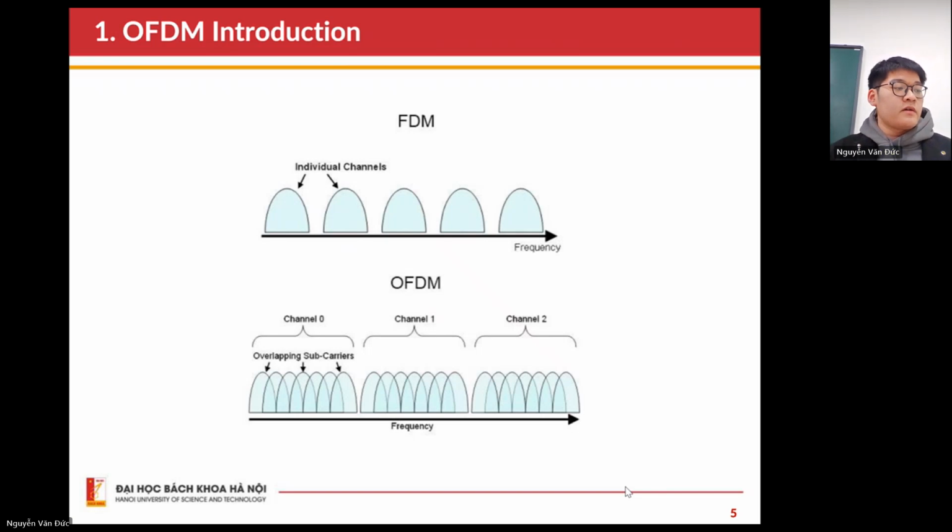I must mention our system, which is frequency division multiplexing, FDM. This is a technique that combines multiple channels with different bandwidths into a single bandwidth for transmission over a medium. Each channel is modulated with its unique carrier frequency, ensuring no overlap between them.